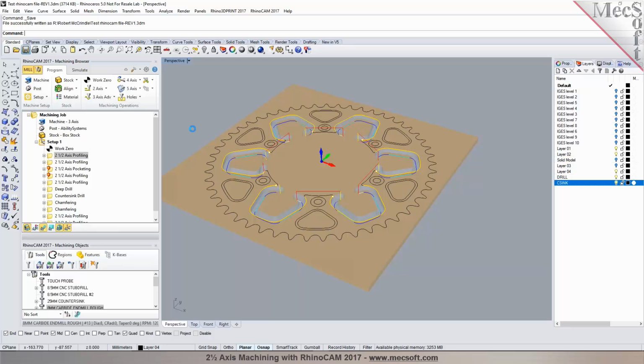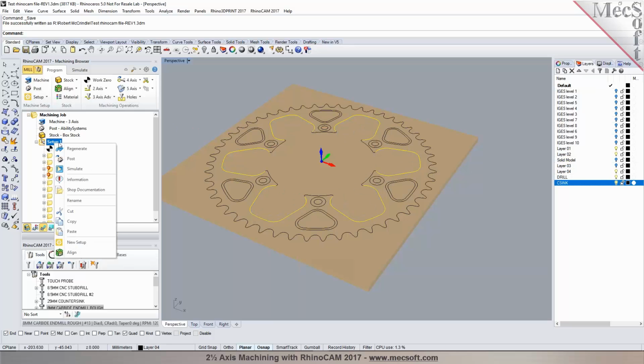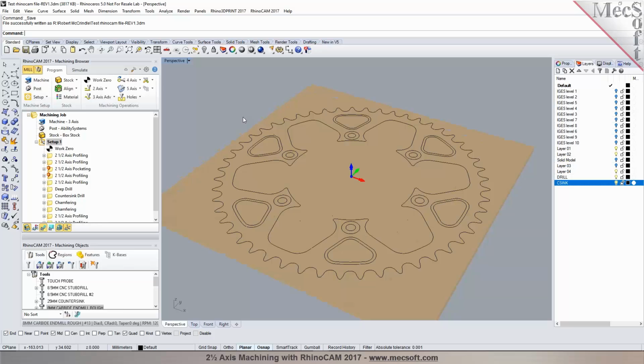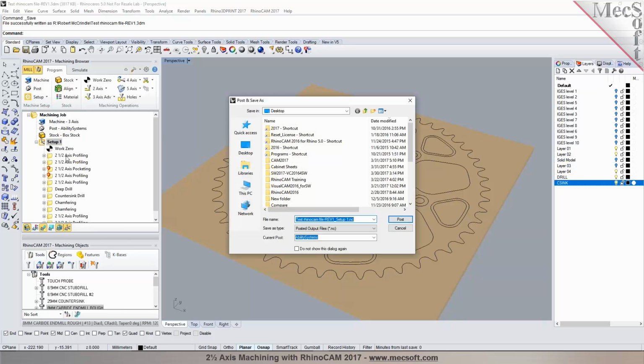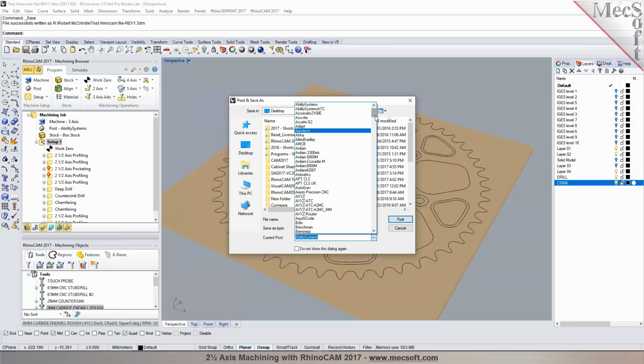Okay. Now what machine controller do you typically work with, so we can go ahead and post process these out to your machine and show you that. It's a Fanuc. Okay, so we'll do a post and we can select the post processor here. So we currently have over 225 different posts in the library of posts that are included, and you can select the post from the list. You said it's a FANUC OM? OIMC, yeah. Okay, so we should have one on the list here, OIMC.